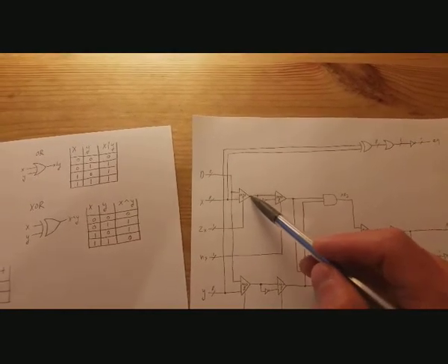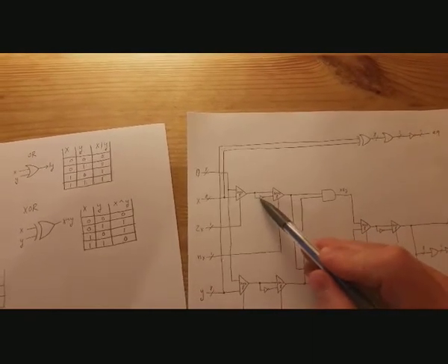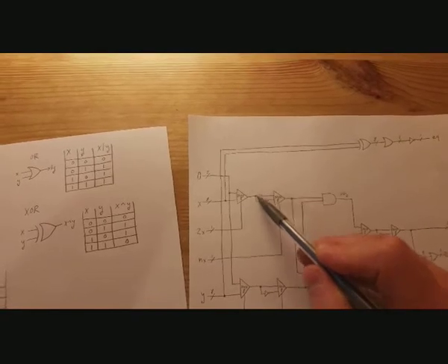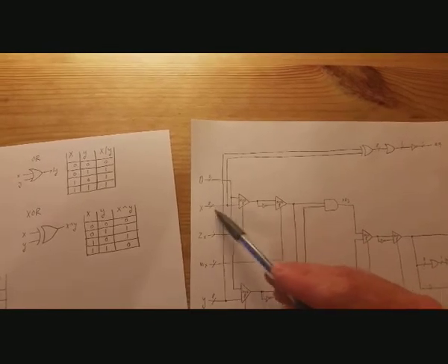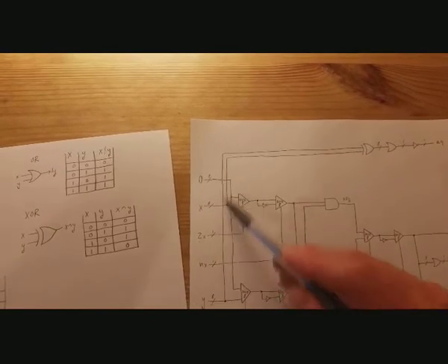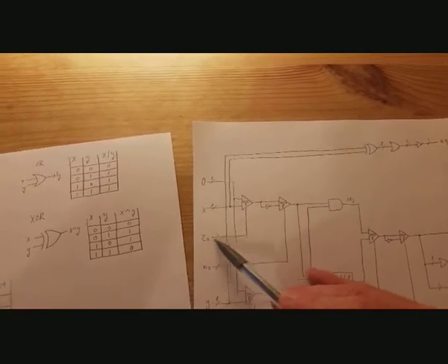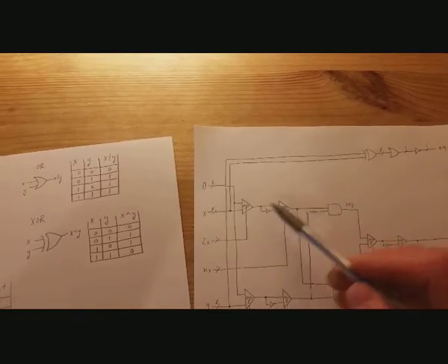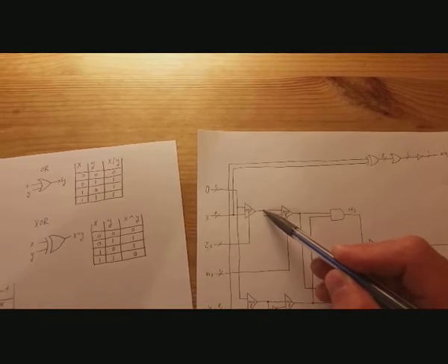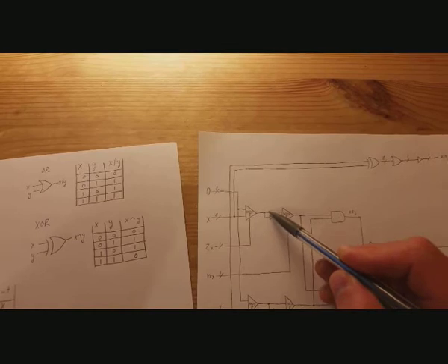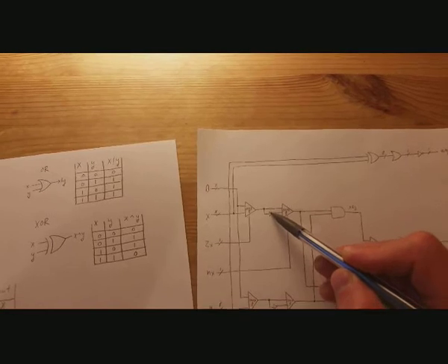So then that's going into another multiplexer with itself, with its bits flipped. The output of this previous multiplexer, whether all zeros or whatever X was, whichever gets chosen based on that control bit, ZX, is going to come out. If you see this dot here, that's just a branch. We get the same values coming down this wire, but on this branch of it, we're going to flip those bits.